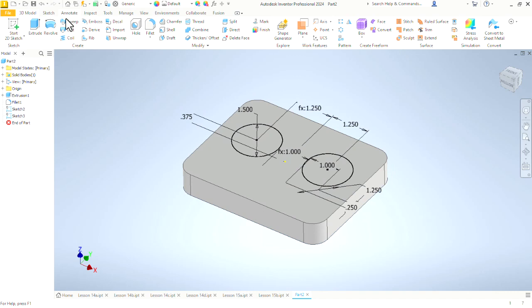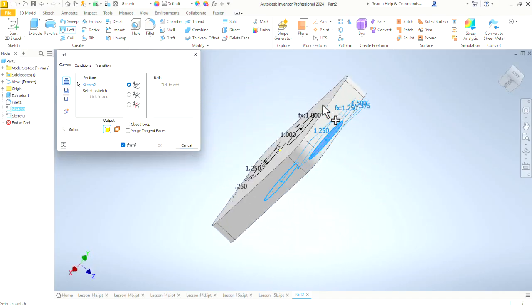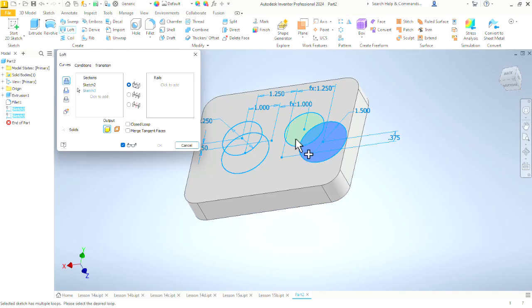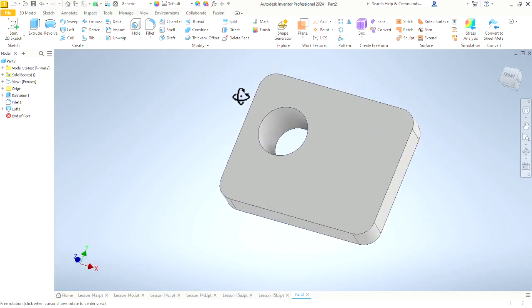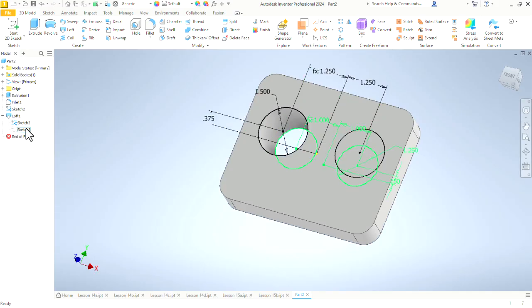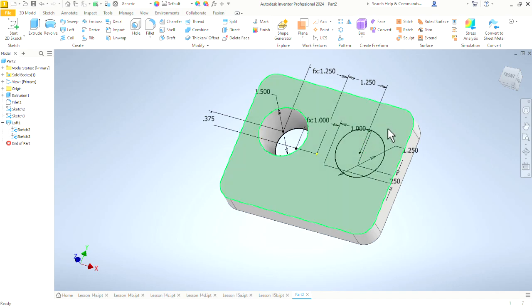Let's cancel that. Let's use Loft. We'll get this profile. Add a sketch. Flip it around. That sketch. That circle. Cut between them. And that worked. Okay. We just learned a lesson, one at a time. Now, I want to create another loft. A couple of things I could do. I can share this sketch. Share that sketch.